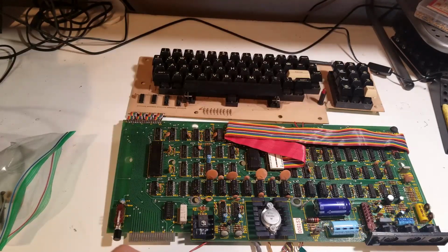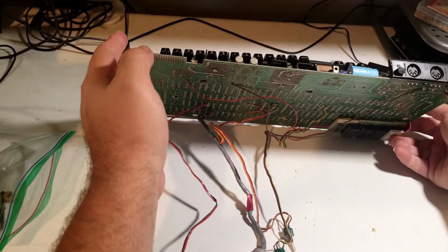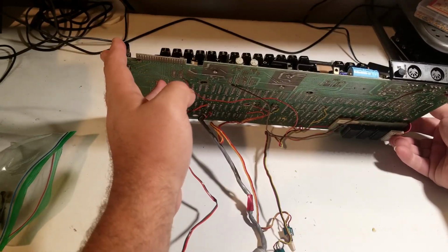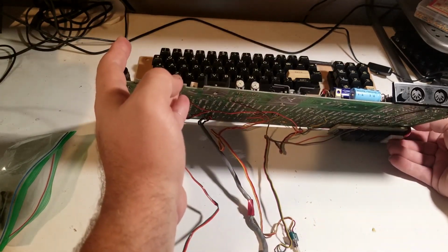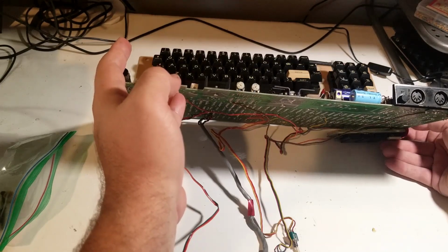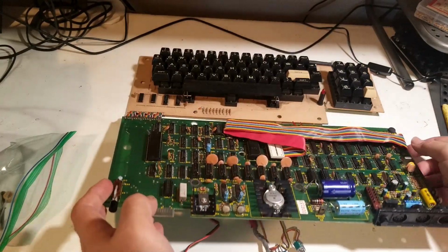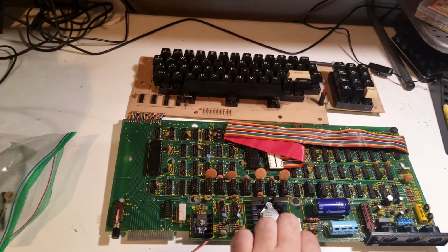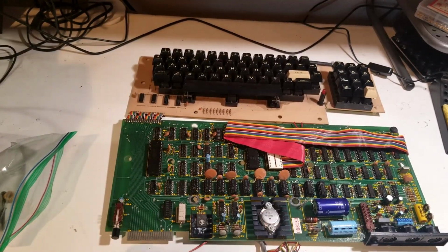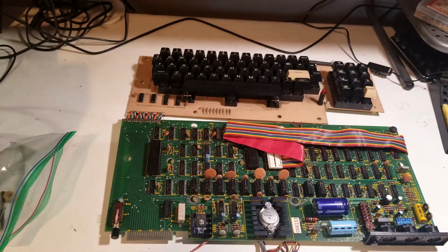One thing that is kind of interesting about this machine is it's got the satellite board for Level 2 BASIC, but it doesn't have the Radio Shack fix. There was an issue with loading from cassette tapes with these, and Radio Shack issued a free fix called the XRX, which worked around the problem. This does not have the XRX satellite board on it, so that's interesting. I don't know if they didn't take it into Radio Shack because they voided their warranty with all this stuff, or what. Anyway, let's see if we can get it put back together.